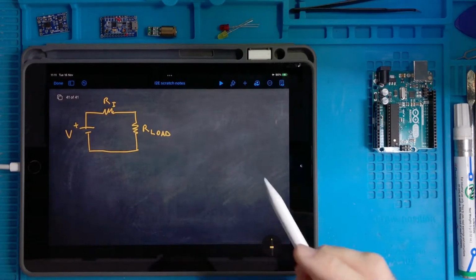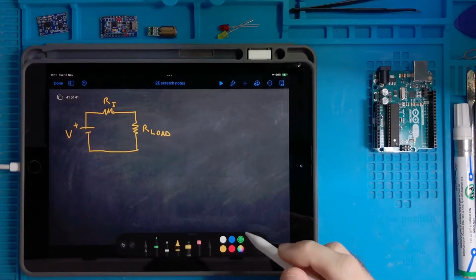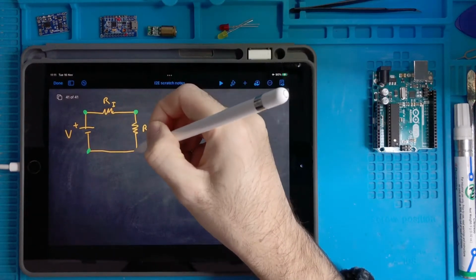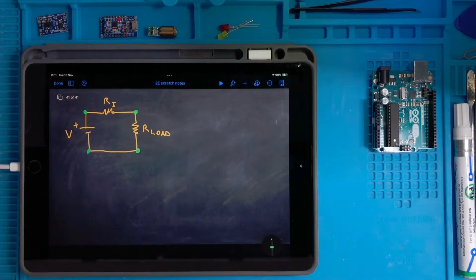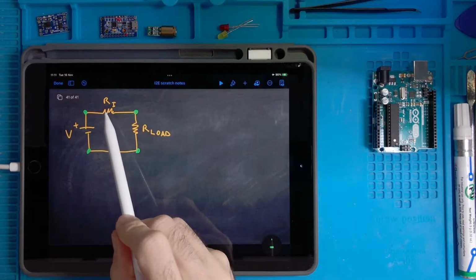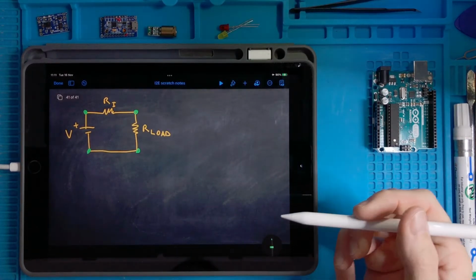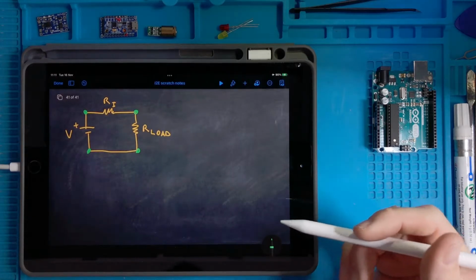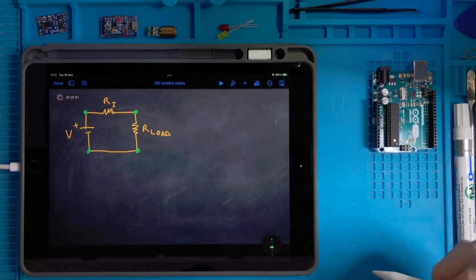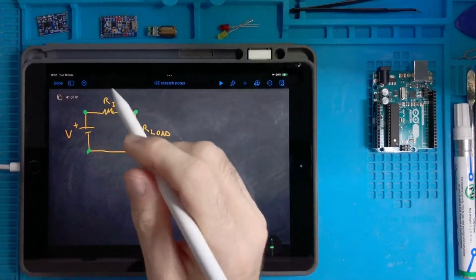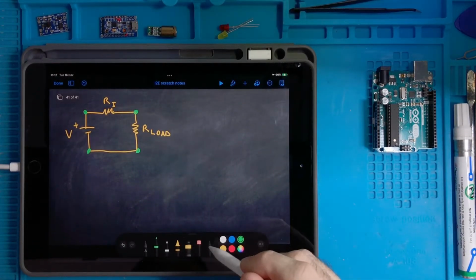in an ideal way. So we ideally want to have the same voltage here to be here. So of course, to have this, it means that this other resistor should be 0. But in reality, this cannot be done because batteries have internal resistances. So what I call here Ri. So our real battery, actually, it's like this.